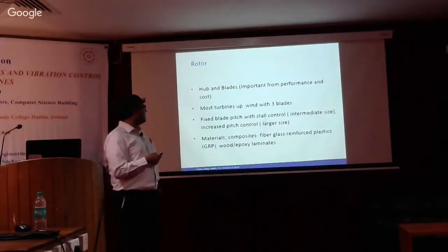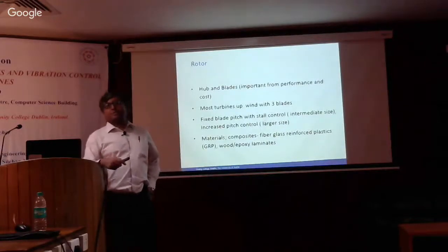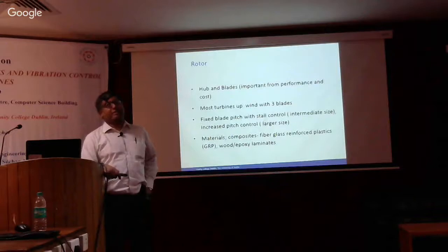I did say that 3-bladed is important, and that's really optimal because by increasing the number of blades, your total mass and design cost increase without much improvement in power efficiency. Also, I mentioned the net force in terms of gravity.